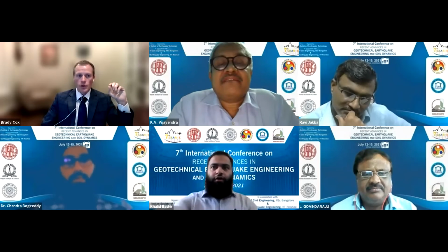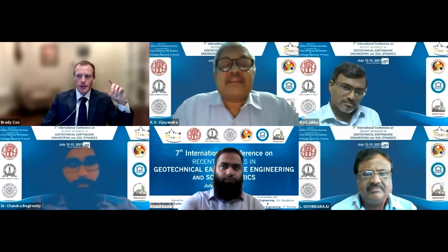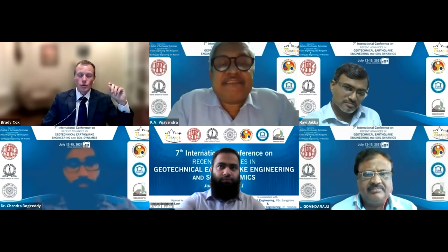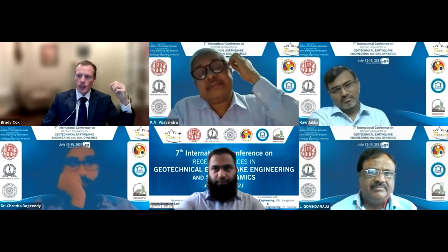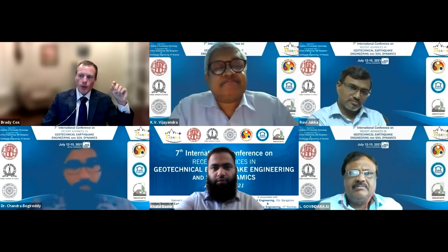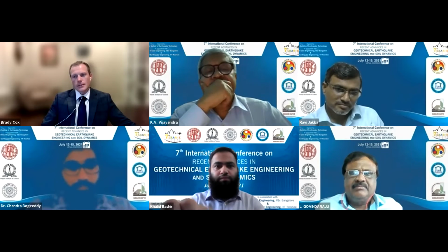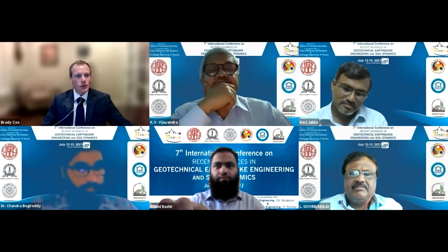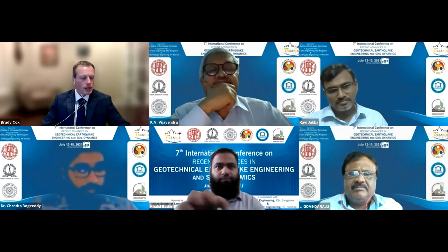And so in cases where the velocity profile is more complex, you might have to spend a little bit more time making sure that you use, for example, boring logs to help constrain what you're doing, using knowledge of local geology. For an inverse, low velocity layer, you're probably going to have to be a little bit more careful, because that's a situation where things may not be as simple. As in all things, there are simple cases and there are complex cases, and in the complex cases, you're just going to have to be a little bit more careful.